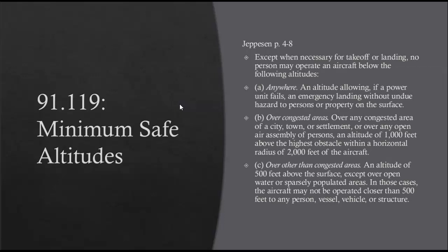And then there are 2 specific rules, one for congested areas and one for uncongested areas. Over congested areas, you need to maintain an altitude 1,000 feet above the highest obstacle and within 2,000 feet of that obstacle from the aircraft.